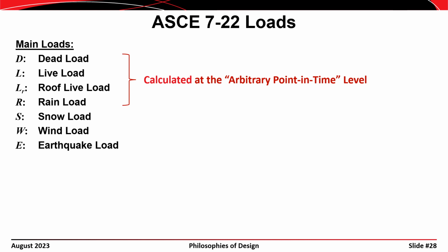On the other hand, when you look at the wind load or the earthquake load, you're calculating the maximum lifetime load that you would expect for your structure. So that's important to bear in mind when we move into our next conversation about load combinations.